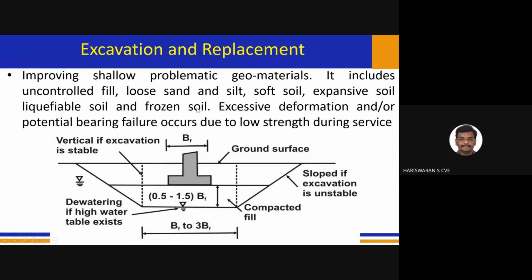The most simple thing is, if you know what load is going to get transferred on the foundation, if we are going for a small scale building, you know the width of the foundation. The significant depth is a maximum of 2 to 3 times the width of the foundation. Up to that depth, the influence will be there. The influence of load transfer will never be for a larger depth, only for a particular depth, measured from the base of the footing. That influence may be up to 2 to 3 times the width of the footing.